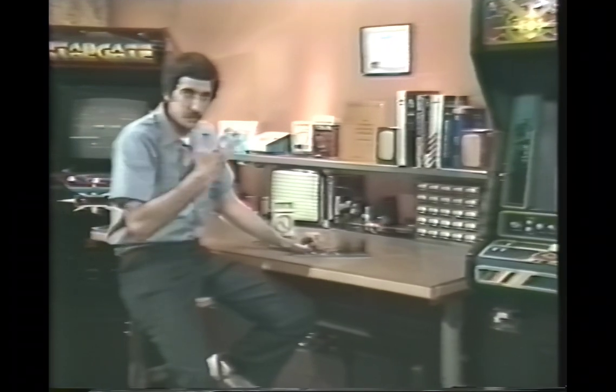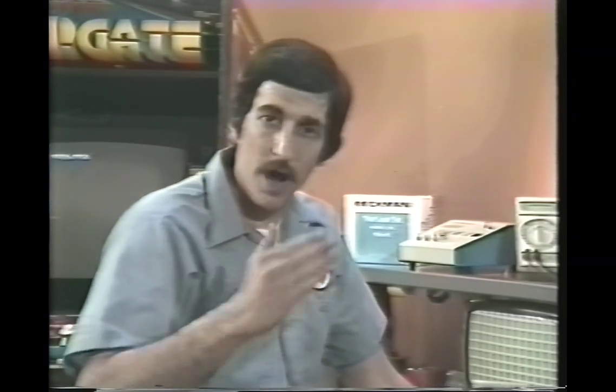Well, now we know how our power supply works, with a transformer to change the voltage, rectifiers to change it from AC to DC, and capacitors to filter out the pulsating DC, keeping the voltage pure. Well, believe it or not, we still have one more thing we have to do to our power supply before we send it to the computer. Remember I said that all of the computers that we use in games require an exact 5-volt power supply. And it can't vary very much. Plus or minus 0.25 volt, or 1/4 of a volt, is about all we have either way. If the voltage starts to drop below 4.75, or it goes above 5.25 volts, the computer will probably start to malfunction.